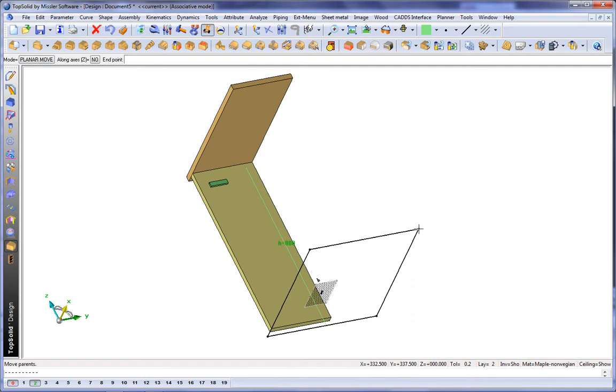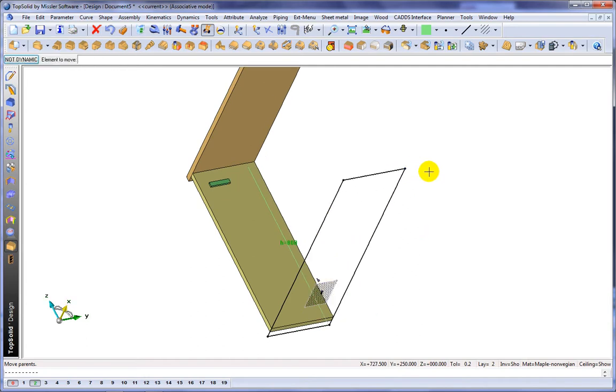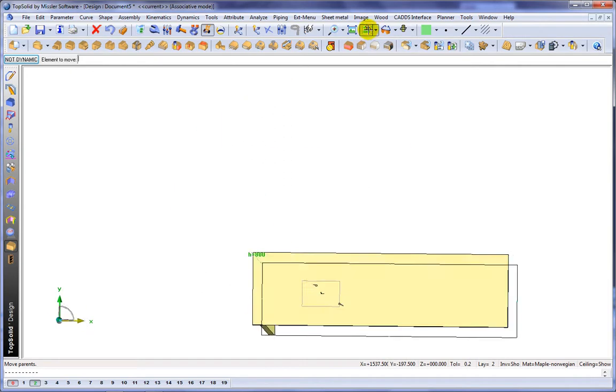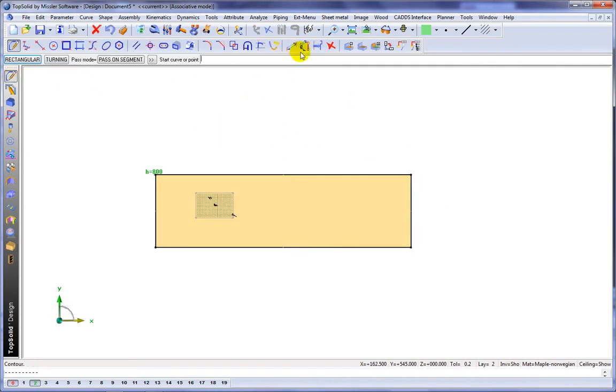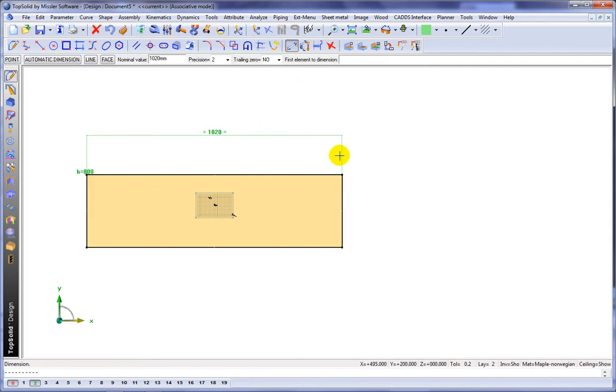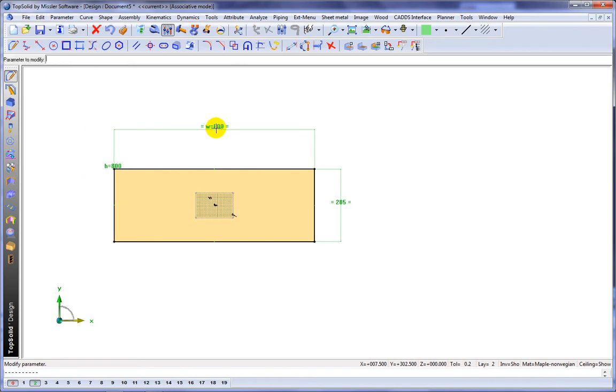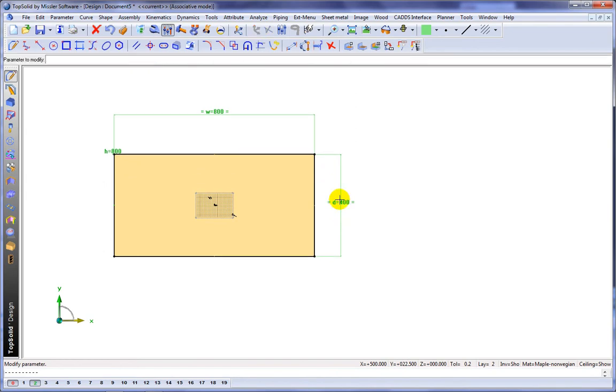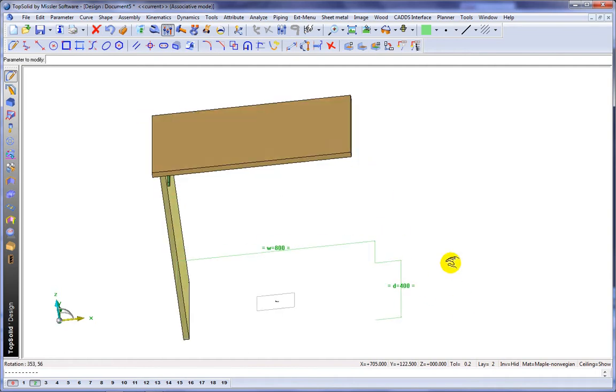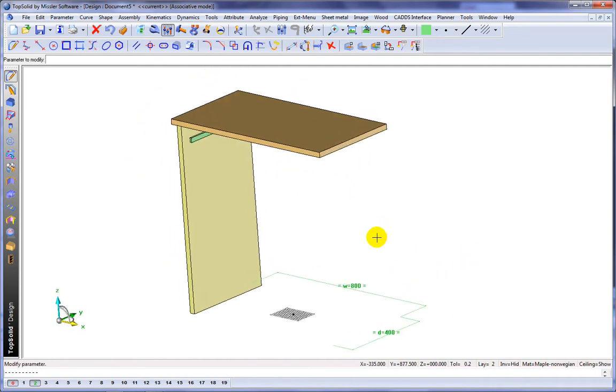Now if you look, if we drag this sketch around that created that initial volume, you can see that our parametric design is doing exactly what we had intended. So now we're going to make it a little bit more parametric, and we're going to add some driving dimensions to that initial sketch. And we'll make them symmetric about our 0. Add this one, make it symmetric about our 0 as well. And then we'll modify them, set them to some kind of fixed value, as well as name them. So you can see, nothing very difficult here. And like that, those dimensions will be used later to drive the overall width and depth of our design.